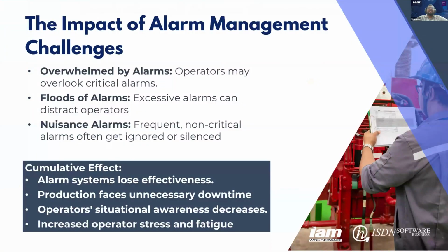Okay. There are a few challenges that we will face in the current alarm management. So let me just go through them one by one. First of all, the common challenge you will feel is alarm overload, or overwhelming of alarms. Too many alarms can lead to alarm fatigue. Why do I say alarm fatigue? Let's say, for example, you have a trip in a pipeline.